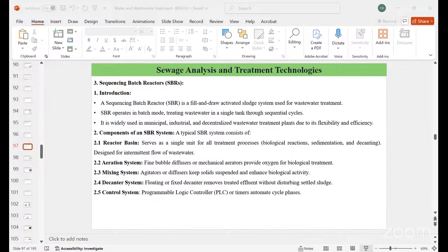Mainly, if you say this is a membrane filtration unit or UV or whatever, this mainly clogs the advanced filters, requiring frequent backwashing and maintenance. And reduced disinfection effectiveness, where the solid particles can shield the pathogens from the disinfectants. All right. So these solid particles, if not removed, the disinfectants cannot directly act upon the microorganisms. So mainly the disinfectants such as chlorine or UV light, which reduces the disinfection efficiency.